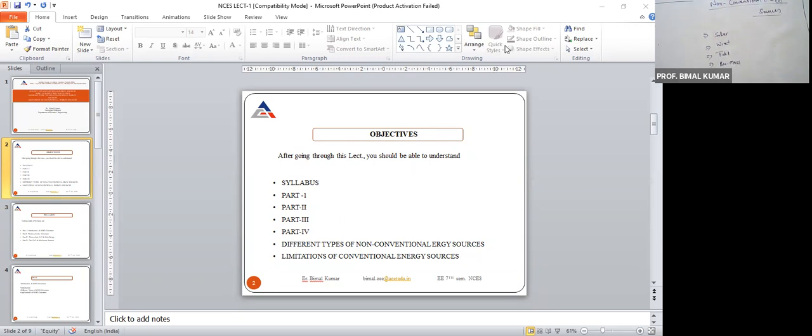right? Similarly, what is the second law of Faraday's? Amount of the EMF induced is directly proportional to rate of change of flux. In first law, what we say is that EMF is induced whenever there is rate of change of flux. And the second law: amount of the EMF induced is directly proportional to rate of change of flux, right? So depending upon these Faraday's laws, we are having a conventional electrical generator.